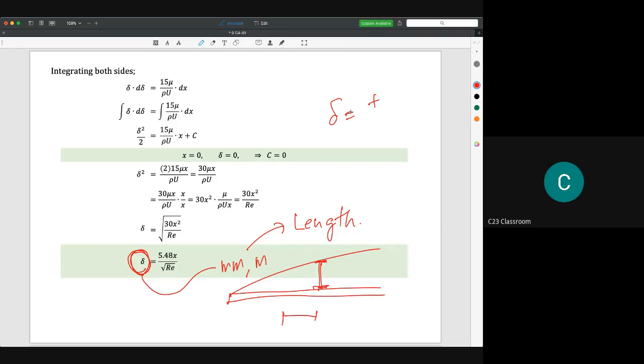So it's small. That's why sometimes if you try to do a boundary layer experiment using a very small plate, for example, just around half a meter or 1 meter, and you are conducting the experiment using maybe a wind tunnel or water tunnel, it is a little bit difficult for you to measure the exact thickness of your boundary layer, because you know there will be some turbulent motion, so you will have some bubbles there, so the flow might be a little bit not steady, so it might be a little bit difficult to determine the boundary layer thickness.